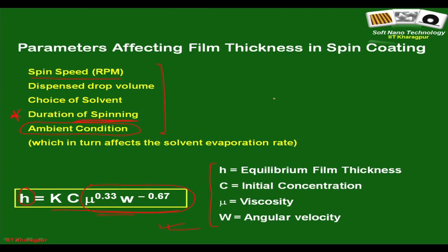Please remember that even when you think that your solvent has fully evaporated, often one finds that about 15 to 20% solvent remains entrapped in a spin coated film.